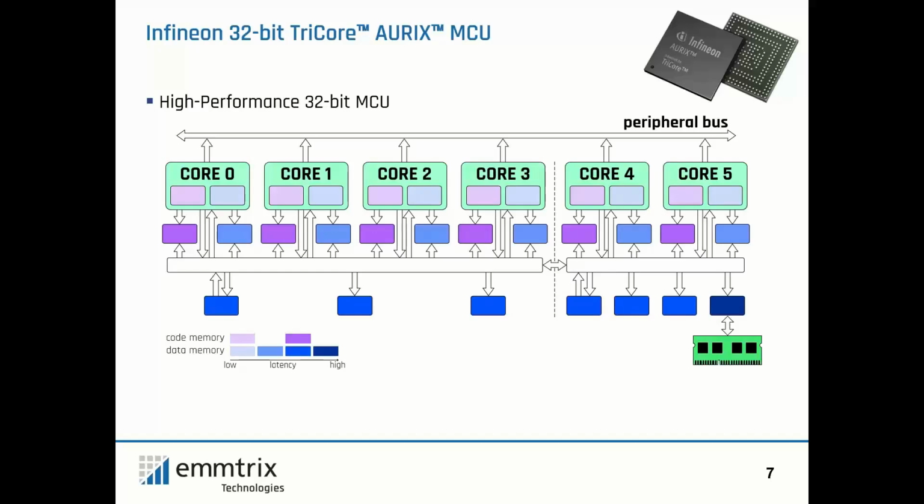And it even gets more complicated if you want to target external memory. So the system is certified for building ASIL-D systems according to ISO 26262. Also, because you can run different applications on different cores, and because of the memory architecture, you can actually isolate functionalities that are running on different cores from each other.